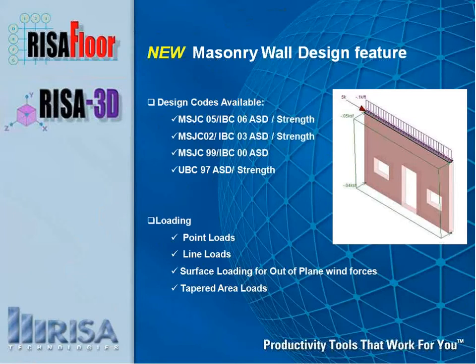As for loading, we can load the model up. We can load a single wall with point loads. We can see on the screen here on the right, we have point loads available. We have line loads along the top of the wall. We can put a line load in for a distributed load. We can do surface loads for out-of-plane wind forces. We can also do tapered area loads. So we have a wide variety of ways to load the model.